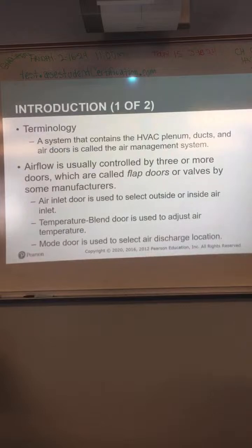Airflow is controlled by three or more doors, which are sometimes called flap doors. These are just doors that open and close to direct air in different positions, okay? If you decide you want the air to blow out on your feet, because that's normally the way it is when you turn your heater on, unless you direct the air somewhere else, it's going to come out of the floor and blow on your feet. Heat rises, right? So if you want it on the bottom, it's going to end up at the top anyway.